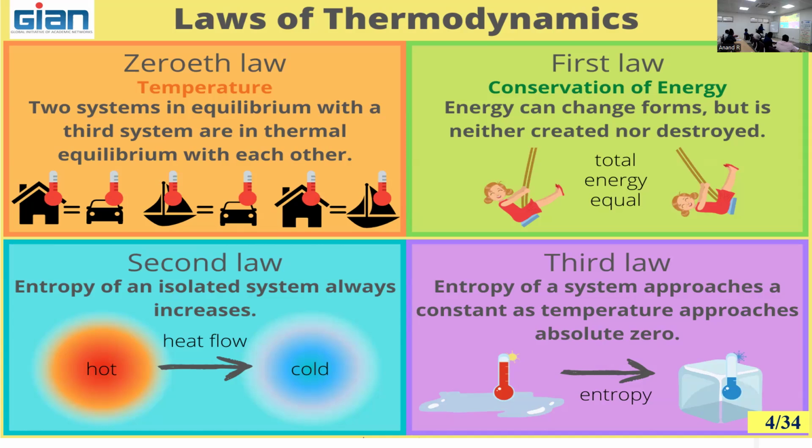Temperature, the sink temperature. Now you tell me, how much is the maximum efficiency I can get? The surrounding temperature plays a major role. People are saying that the efficiency of a petrol engine is maybe around 28 to 30%. Diesel goes with 30 to 35.